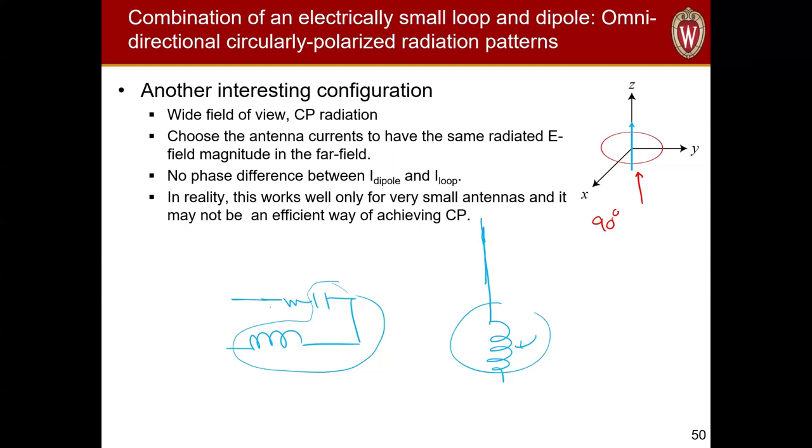But for a small antenna, the real part of the input impedance would not be 50 ohms, so you need to use a tuner. And I think either one should work well. I don't see any significant difference between the two ways of modeling that. Thank you.